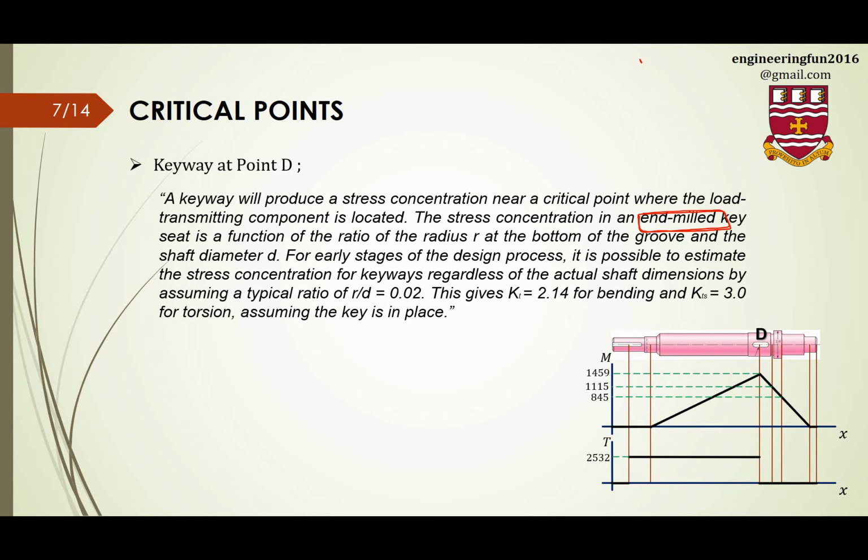The stress concentration in an end milled key seat is a function of the ratio of the radius r at the bottom of the groove and the shaft diameter d. So that is a function of r and d.